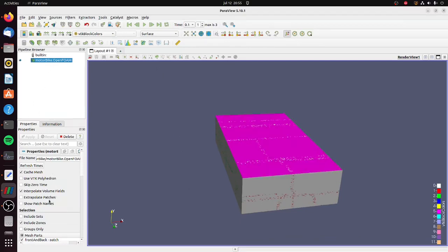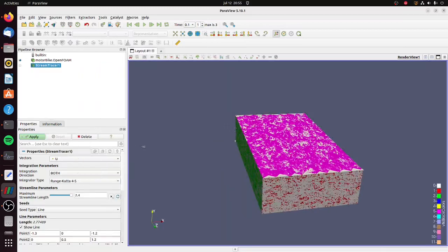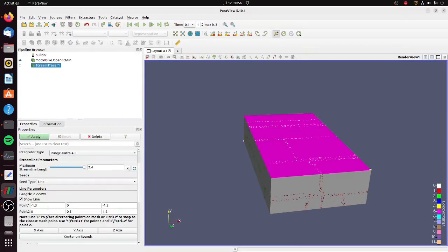But okay. And then we'll just recreate what I did to start out with. So we'll do the stream tracers. So this is the stream tracer button, and then you pull up all these options for stream tracers. Ooh, that was glitchy. And then what it's saying is that it'll do it on a line. So we need to come up with some good points.